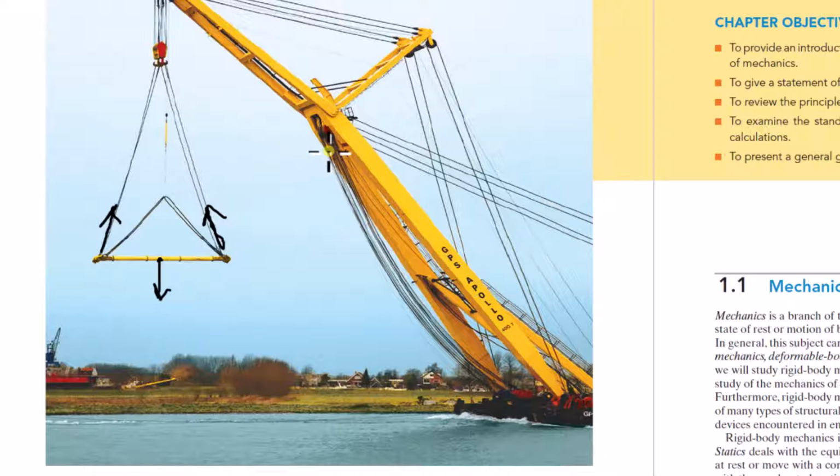But for the sake of finding the moment load and the vertical and horizontal loads that are holding the beam, and the loads here, for the sake of finding all those loads, you don't need to consider how the lines of action of these loads change because of that small beam deflection after lifting the load. That would be completely unnecessary. You would be getting differences in your final answer of 0.00000 something percent. So there's no need to add that complication.